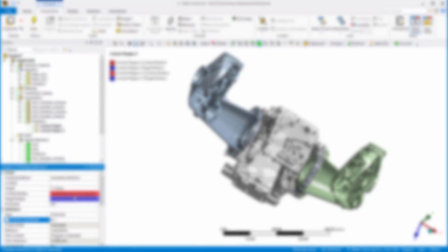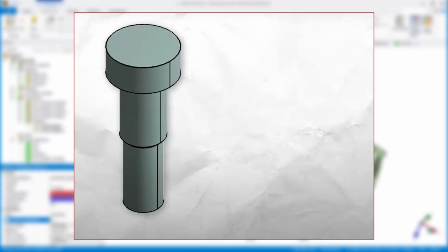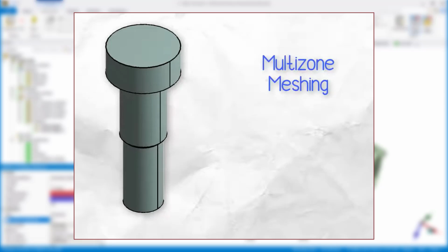The next step is to define mesh controls. The bolt geometry without the threads and with the circular head resembles a series of cylindrical portions. So to create a uniform mesh, we'll use the multi-zone mesh method, which splits the domain into multiple zones and tries to mesh them with uniform mesh. We'll define this on 2 sets of bolts.